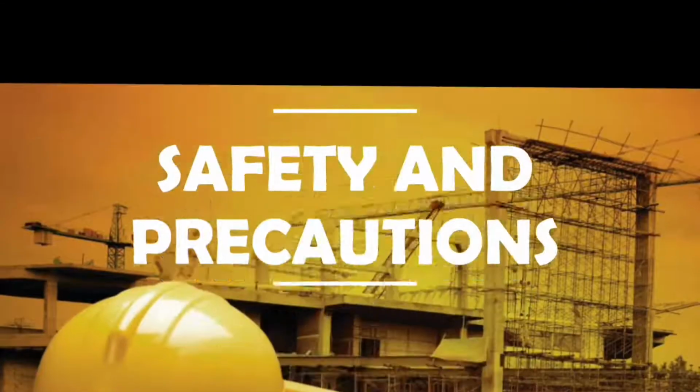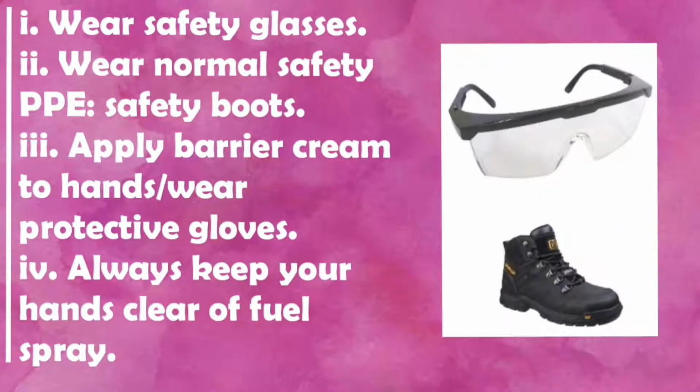Safety and precaution. Wear safety glasses. Wear normal safety PPE overall, like safety boots. Apply barrier cream to hands and wear protective gloves. Always keep your hand clear of fuel spray.